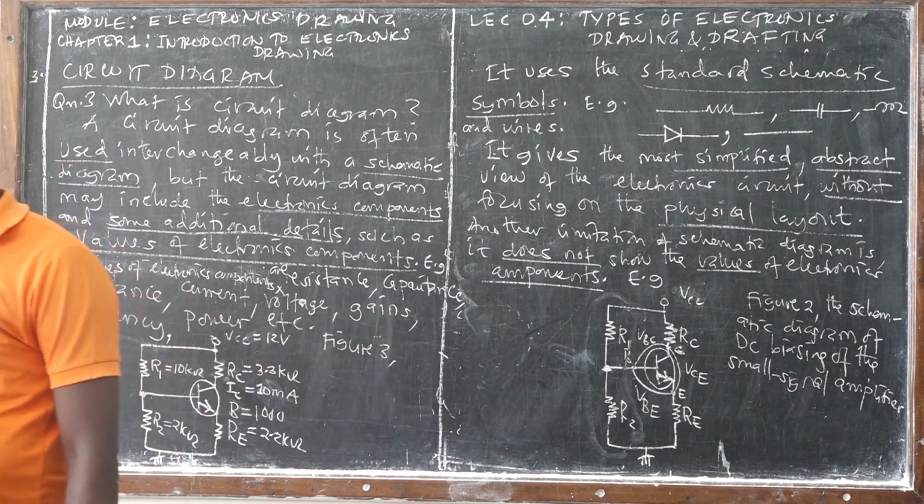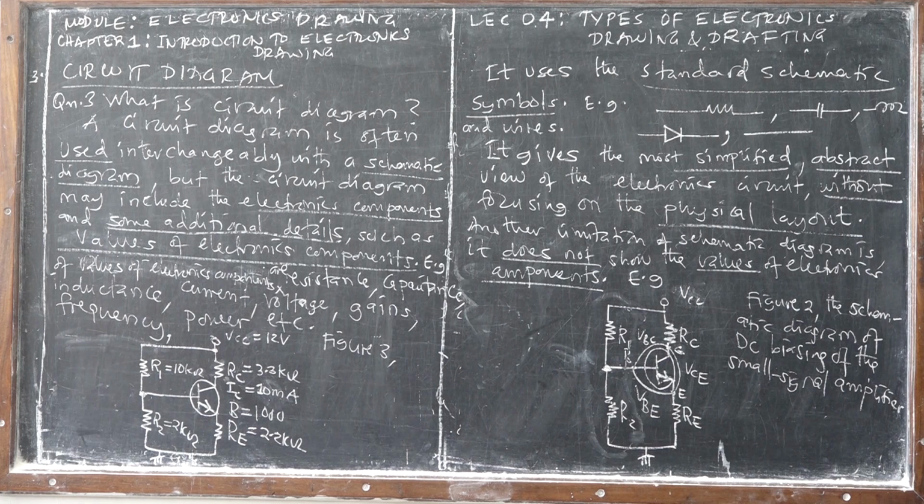small signal amplifier. When it comes to circuit diagrams, we need some detail. And those details, when you draw them, that is schematic, because the circuit diagram is just an advancement of the schematic circuit diagram. Then we need to know what the power supply for our system will be. That's why we define it as 12 volts. It might be 12 volts, 15 volts, 9 volts, or 5 volts, depending on the design. Then what are the values of these, which you call the potential divider network?